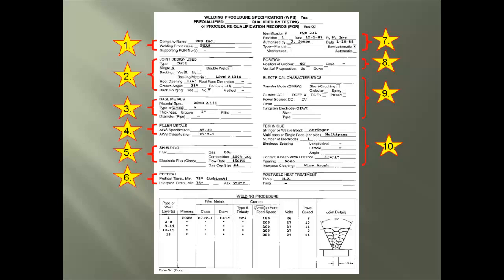Next, are multiple electrode heads being used, and if so, what is the spacing for those heads? If flux core or gas metal arc welding processes are used, what is the contact tube distance from the weld joint? Is there any manual tooling to the individual weld bead, called peening, being used? And closing with the means of cleaning the individual passes.